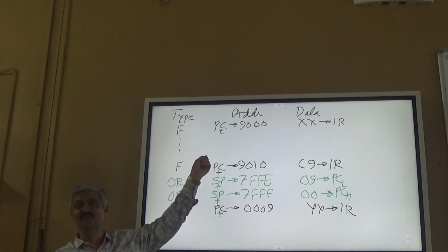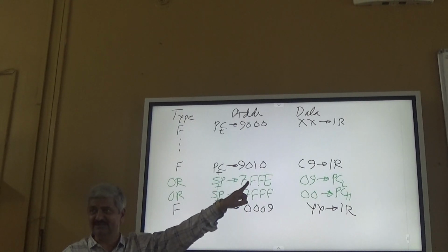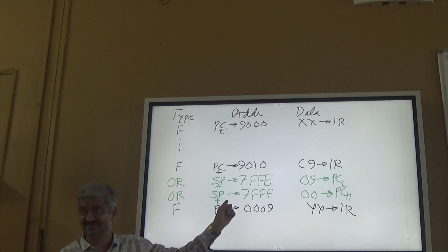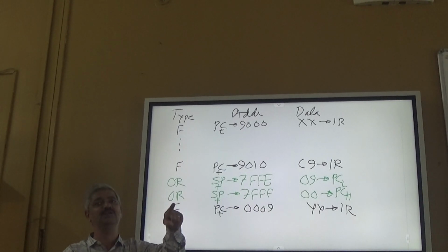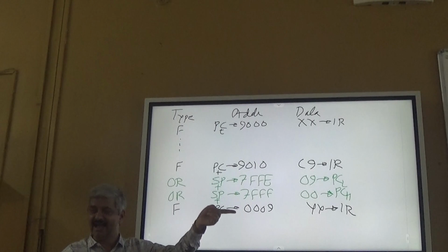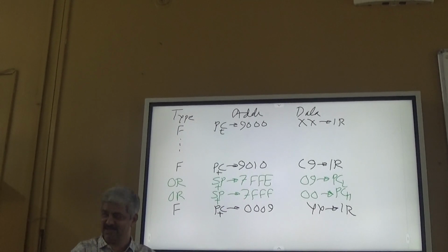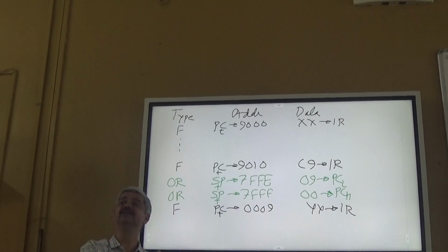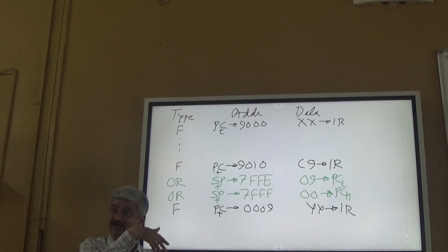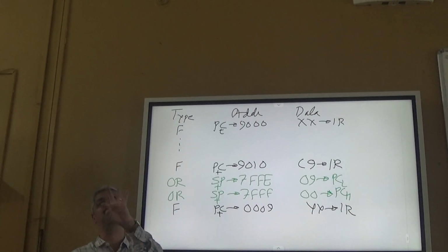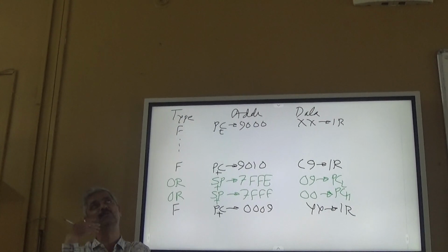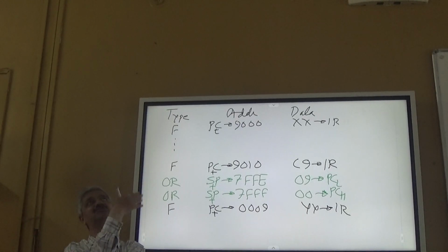But here the main program uses a subroutine that is executed on the same processor. So what is my subroutine doing? My subroutine multiplies H and L and stores the result back in H and L, but the subroutine is using other registers: A, E, D, and one counter B. So these four registers, B, A, E and D, are being used by my subroutine. Suppose before calling the subroutine I have some application in which these registers are also meaningful.